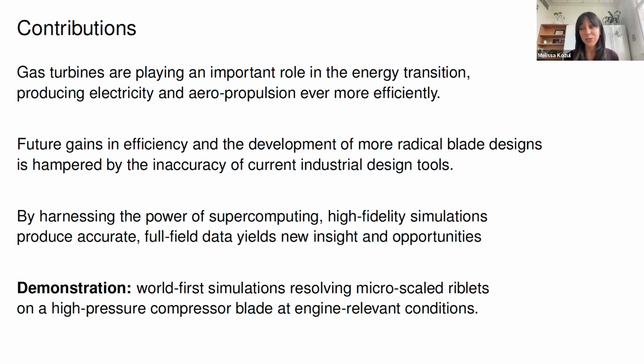Basically, the turbine blade gets very rough from a range of reasons, and those ceramic coatings crack, for example, and that changes the transition point very much so, and really increases the heat transfer and therefore the danger zone for that turbine blade. Oh, fantastic. Thank you very much. Thank you.